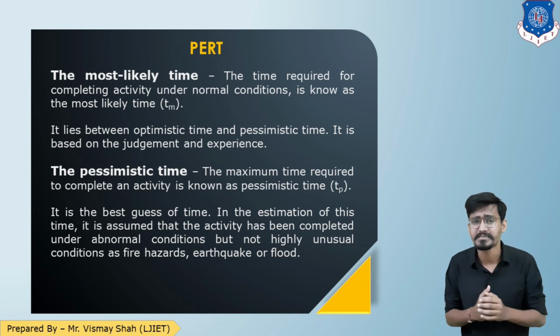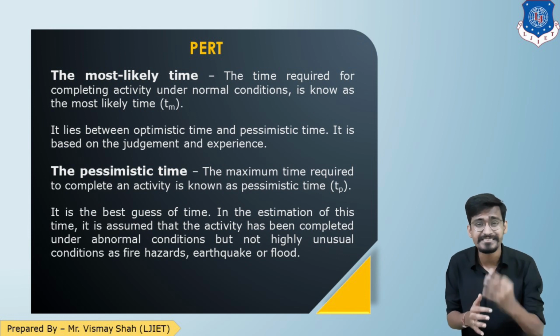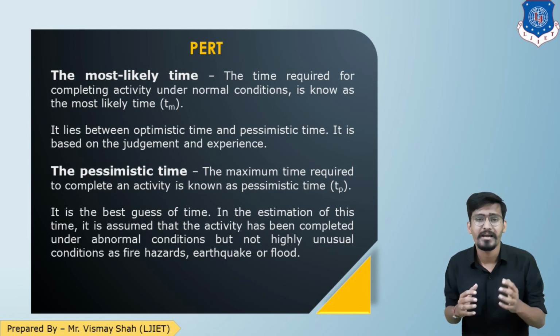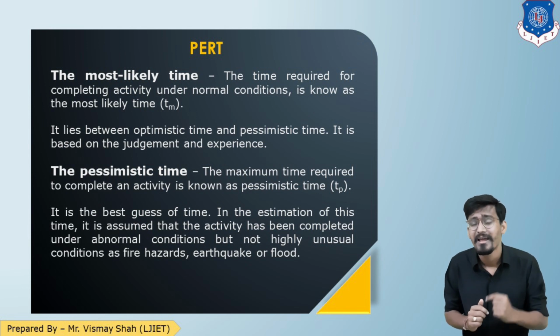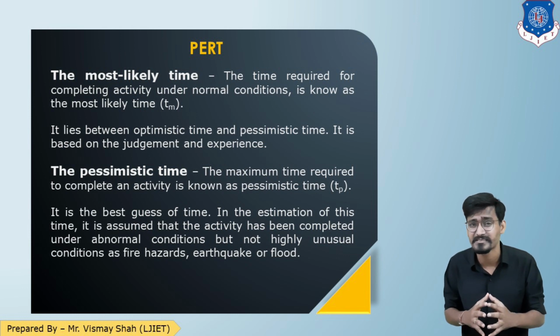But now students, in the CPM method, what do we do? We were given the activity and its duration, then we performed the forward and backward pass. But here in the PERT method, three estimates are given. For example, if we talk about excavation, in the CPM method it was given that excavation takes 10 days. But in the PERT method, excavation can either be completed in 5 days, or in 7 days, or pessimistically, late, in 10 days. So how to represent that?